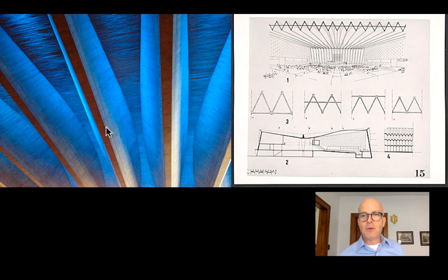And Nervi arranges that curved line so that it is putting more material in the compression area of the basically long-spanning girder at the top here, coming down and being in the tension area as it comes over the supports, and that is tuned again to the moment diagram.